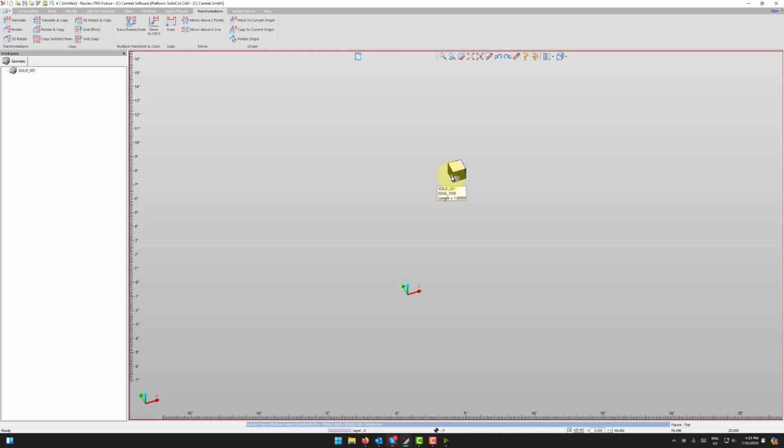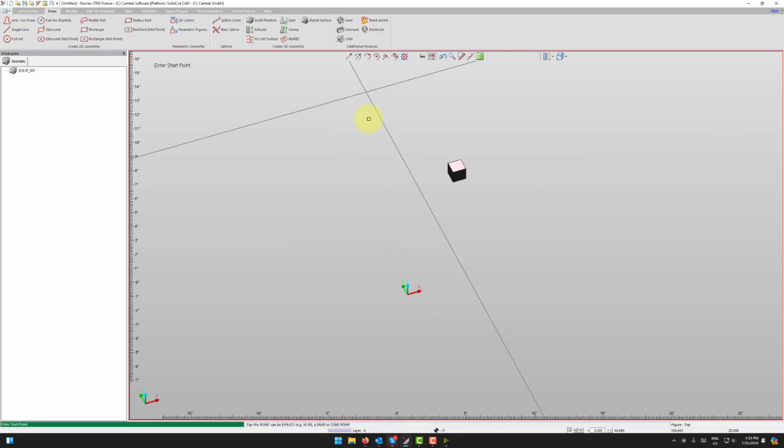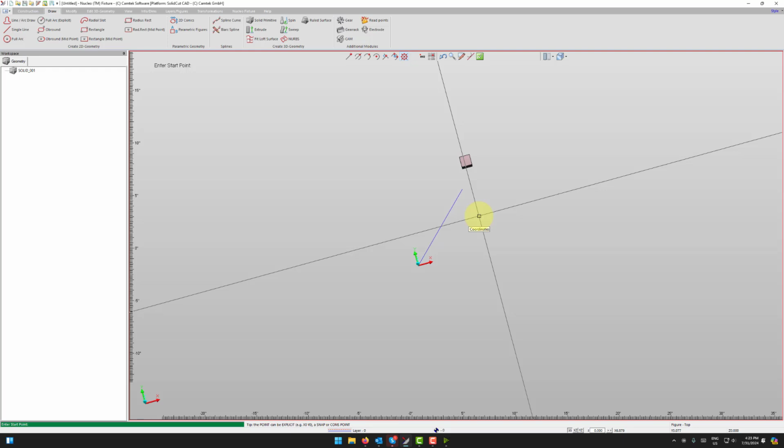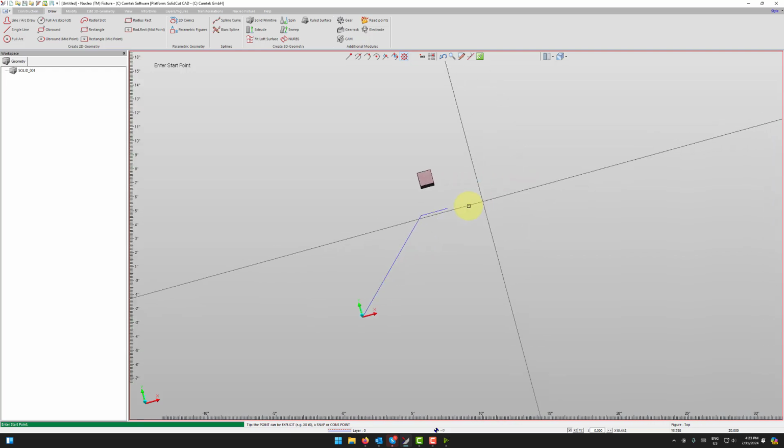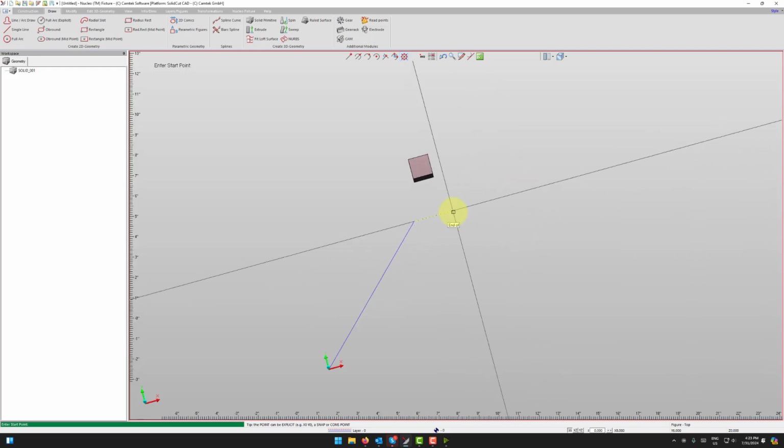Right. These very same tools can be used when manipulating boundaries, clamps, and even drawing. If we go to the draw menu at the top and use the single line tool, right, we can snap to the origin here. And you can see I can type in B, 45, and then distance in X, 6, press enter, and you'll see again a 45-degree line that's gone over 6 inches in the x-axis. Right. We can continue drawing while we're in this drawing tool. I can snap to the end of this, and I can say distance in X, 2. It goes over exactly 2 inches in X for us. So we can use this while drawing as well.